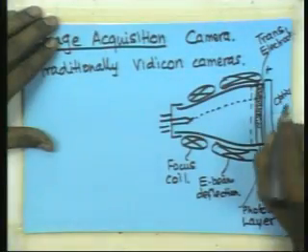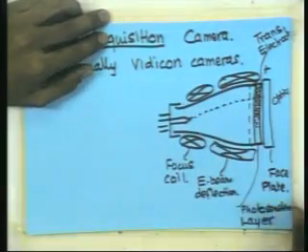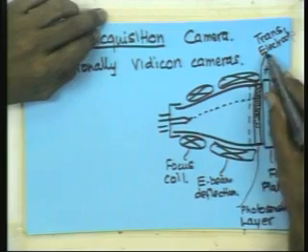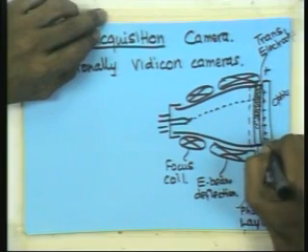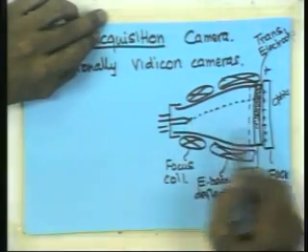What happens is, supposing there is no light coming, this portion here is optics, which means your focusing lens, etc. will be there in the camera, and behind that is all this stuff here. So, when there is no light coming at all, then this positive charge will be distributed. There is a good conductor here, so you will have positive charge existing here, and we are depositing negative charge here.